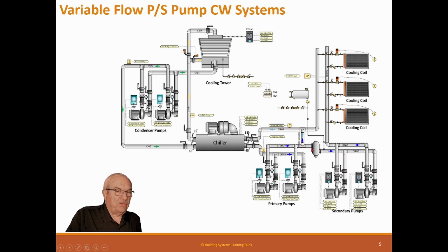A lot of times, if you have it where instead of this one into the suction of this one, they're both sucking off the return, then the water always goes the same direction to the decoupler. It means it has twice the flow to the decoupler, and it can't do that. So that's why you have a chiller restriction on those jobs. So now, why would they ever install it that way?